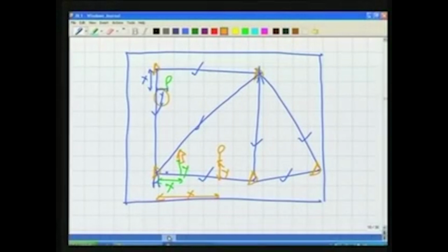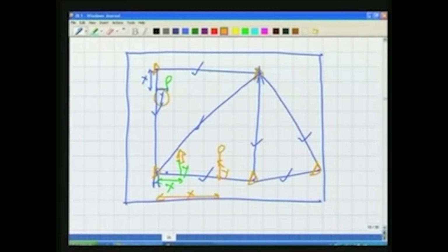The next principle. Here itself, we have taken utmost care and measured these lengths. What if some of these lengths are measured with error? What will happen in that case? Let us say this L3. When we measured it on the ground, we measured it with some error. What will it do? It will distort my skeleton of the area. All the measurements which I carry out later on will have some error now. My map will be distorted.